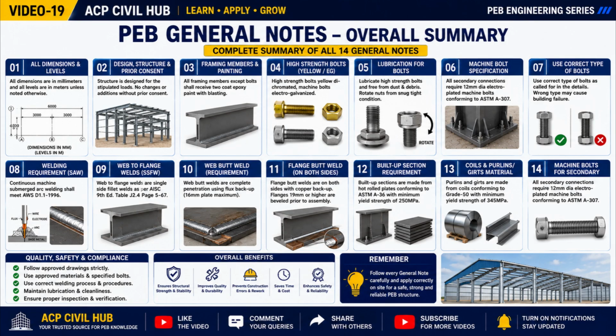In this video, we have completed all 14 general notes of the PEB General Arrangement Drawing. We started by understanding drawing units and structural design limitations, then learned about epoxy painting, bolt specifications, lubrication requirements, and secondary connection bolts. Next, we covered the importance of using the correct bolt types, AWS welding standards, web-to-flange welds, web-butt welds, and flange-butt welds according to AISC requirements.